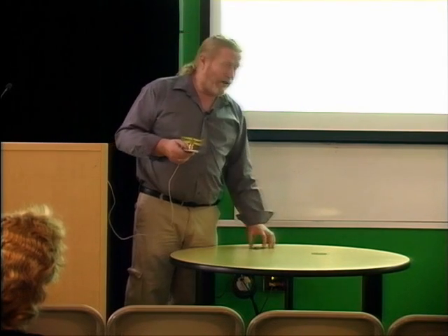This one is better. The penalty of going up in frequency is you reduce your penetration, but the advantage is you can make smaller antennas. You can still make small antennas for lower frequency, but your efficiency is degraded.